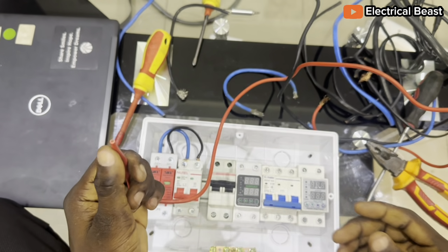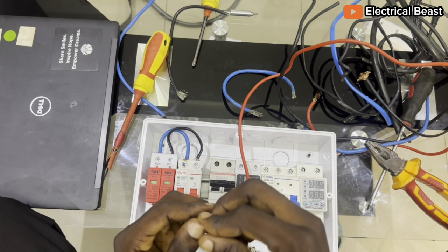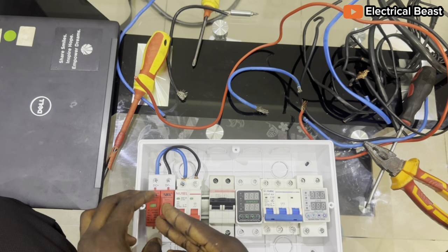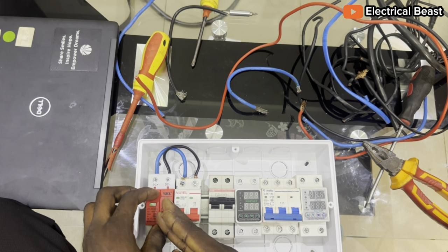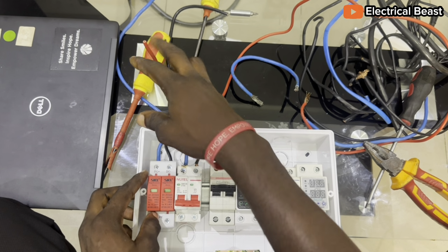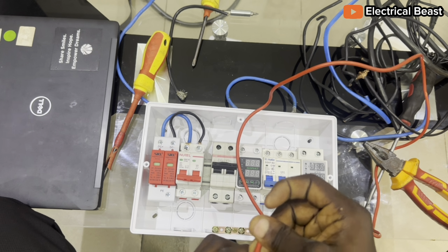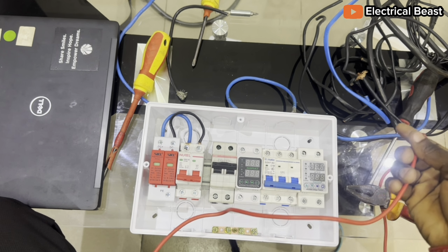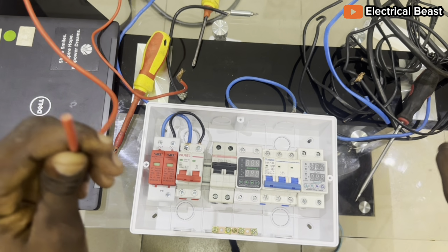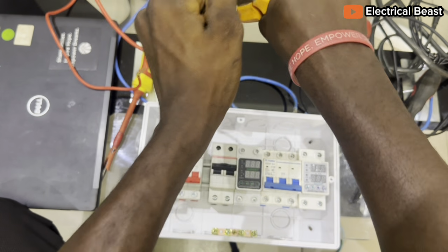Use an AC cable. Depending on the size of your system, that will enable you to know the size of cable that you should use. For the DC side, most times we use 6 mm or 10 mm cable to do the connection for the breakers and the surges. Then for AC, depending on your system, if it's a 5 kV or a 10 kV system, ensure you use nothing less than 6 mm. In most cases, sometimes you can use 10 mm flex cable. It's best practice to use flex cable because the connection is more secure when you use flex than single strand.